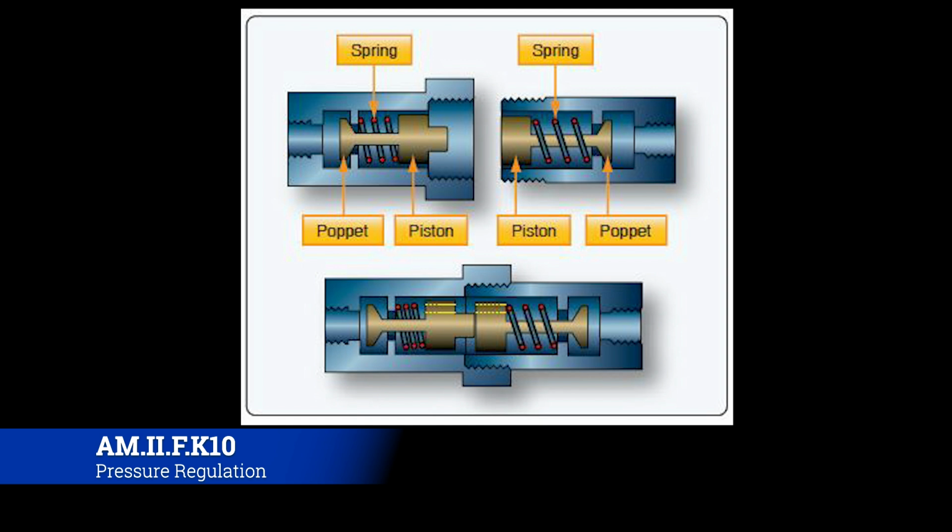We used it frequently to find leaks. There's a lot of things you could do with it, but what I remember the most is hooking up the AGPU, turning the hydraulic pressure on, and looking to see where the leak was. You'd clean the flight deck up really nice, turn the AGPU on, and wherever you start to see the little red drips of 5606, that's where you went and started working on it. So that is a quick disconnect valve. It's a really cool little device.